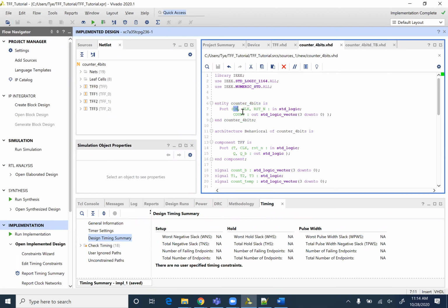Look at my top level. These ports, CE, clock, reset, and count, are all going to be outputs to the real world, if it's the top, right? So for an internal module, it can just be connections internally between modules inside the FPGA. We've dealt with that repeatedly. If it's your top level module, that is what's expanding out to the physical pins. And that's where that constraints file came in. That example that I gave you is to tell it what pin this port attaches to. So all top level ports go to your constraints.